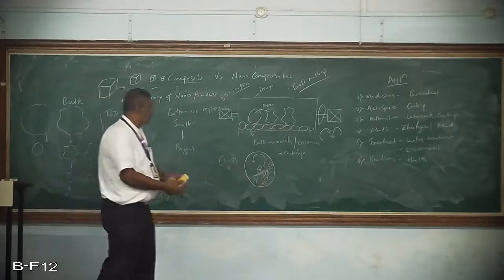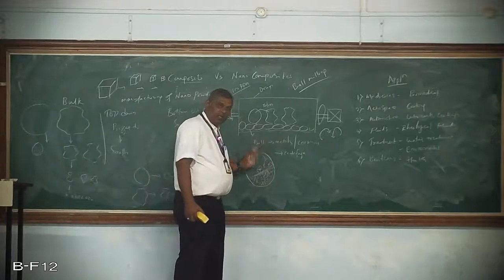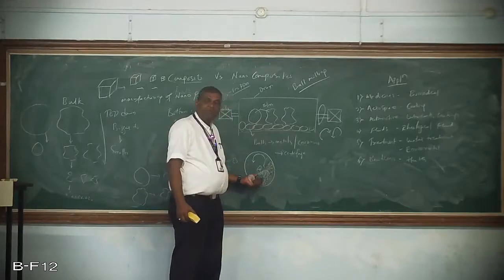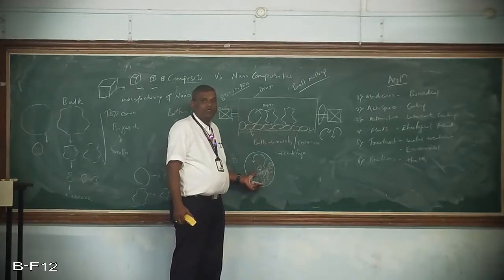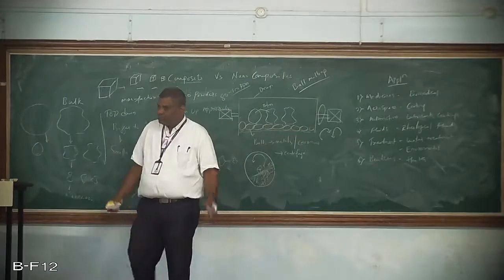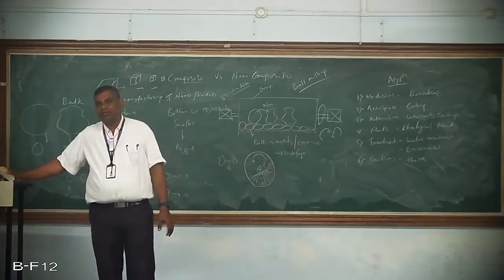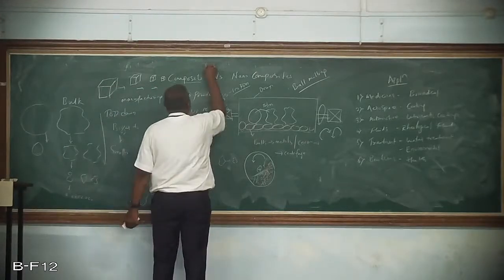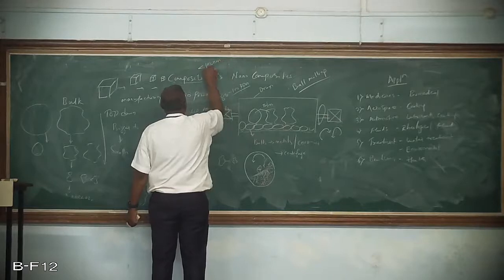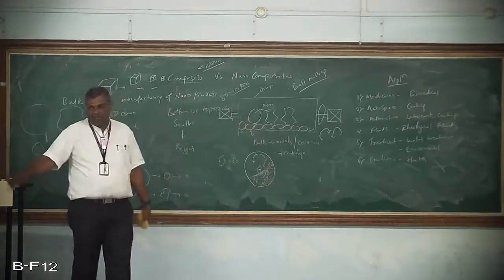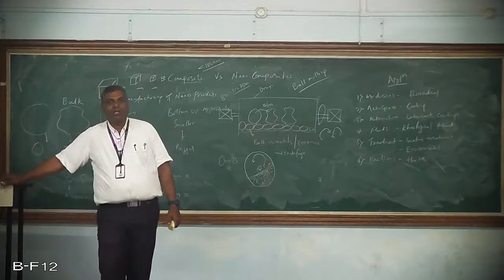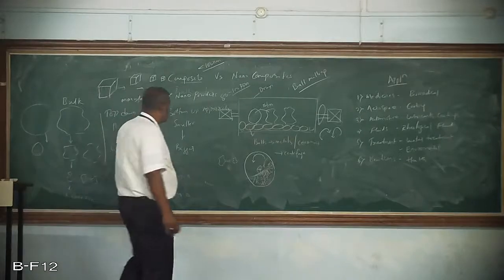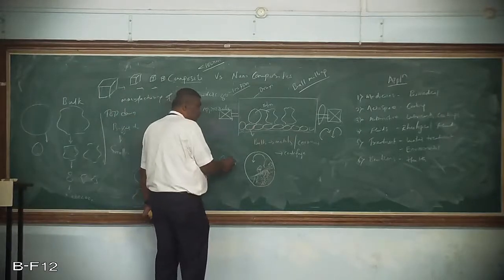So then what will happen? The ball comes up here and falls down. While it is falling down, it falls on this raw material. So the raw materials are broken into smaller size. It is ground to such an extent that it is converted to fine particles, with particle size in the order of less than 100 nanometers. So it takes a lot of energy and a lot of time to convert from bulk material to powder size. But one thing we can see here, the conversion ratio is high, but the efficiency is less.